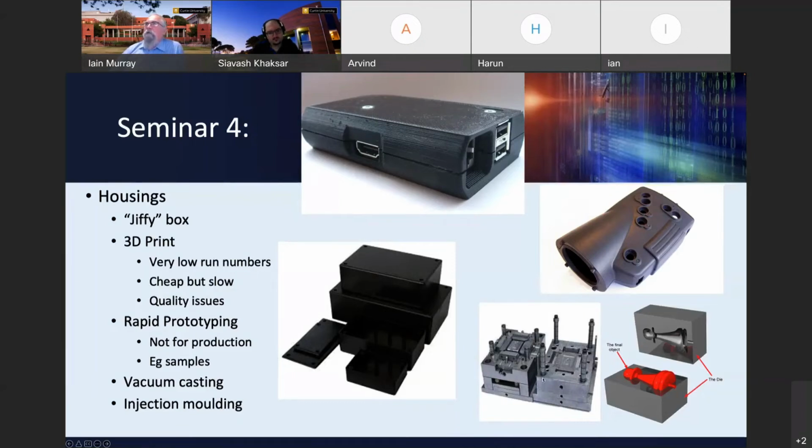The reason I was involved in that is I'd actually developed a robotic system to mill these devices out. We would start our prices at around $40,000 a mold, 40,000 Australian dollars a mold. So if you're looking at your production run, you've got to recoup that $40,000 over the production life of your device. And that means it's a fairly hefty investment to begin with. I will again say they don't cost anything like that now. I don't know how much they are, but you still have a very large setup cost and a requirement to run off very large numbers of your device, your casing, to make it viable.